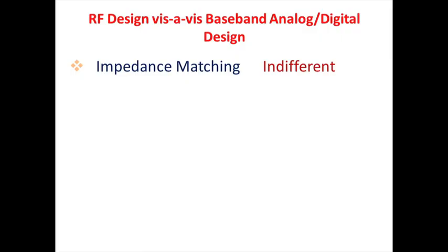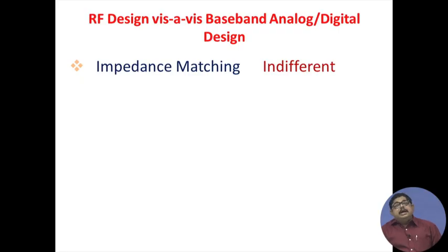That is why they take a lot of care for this impedance matching, whereas we can say that the analog or digital design are indifferent to that. One example I will say, when we design a C amplifier, we try to say that our design goal is to maximize the input impedance and minimize the output impedance. But from the maximum power transfer theorem, we are not at liberty, because whatever the source is, we will have to match to that